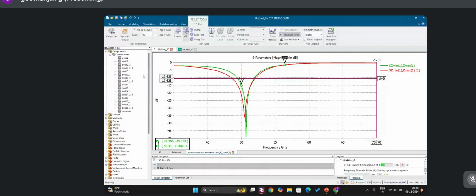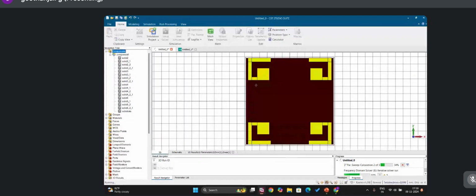So, by designing the bandstop and bandpass FSS and by combining it with the incorporation of pin diodes, you can design a multifunctional FSS, which is a trending hot topic now. And you can also design a radar absorber, which I'm doing my research in. So it is called a frequency selective rasorber, which is known as FSR.